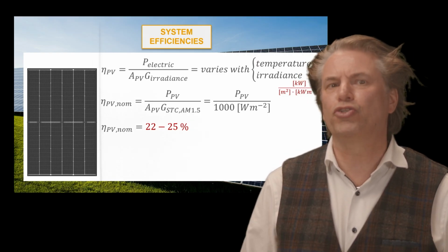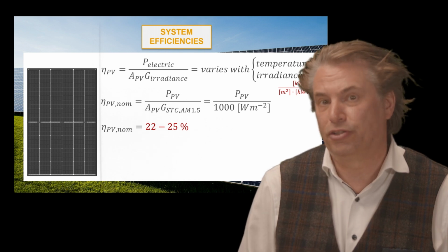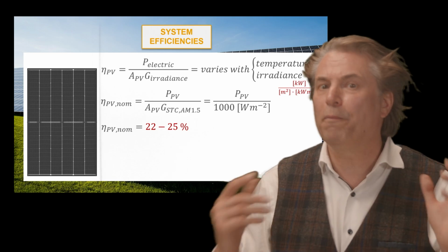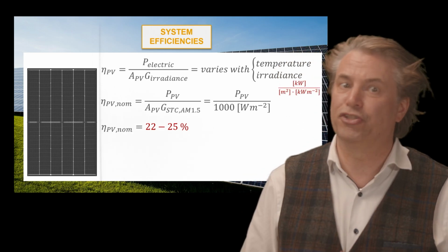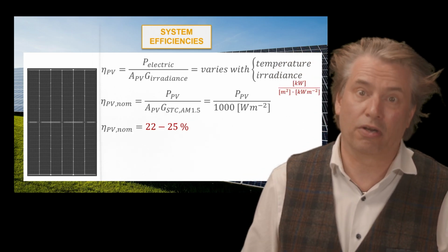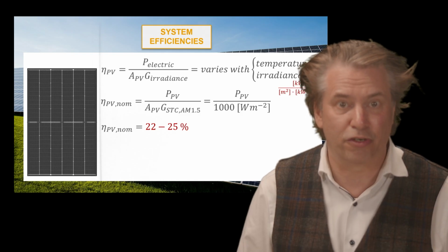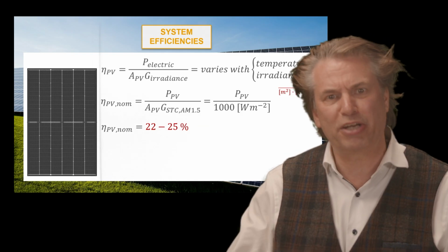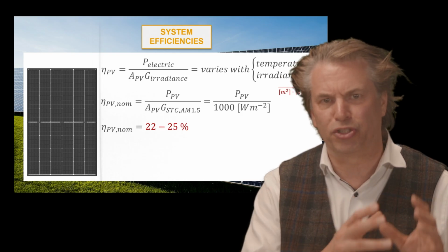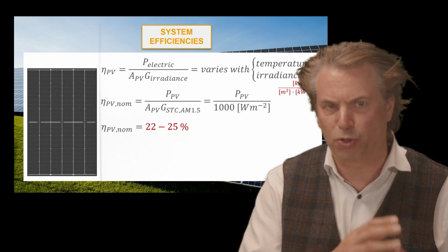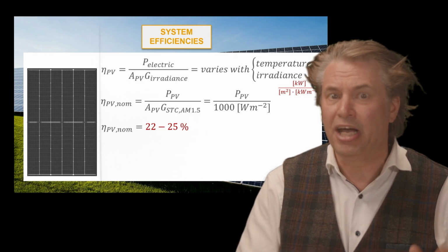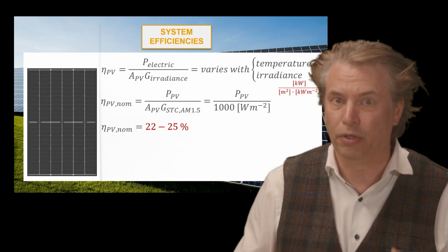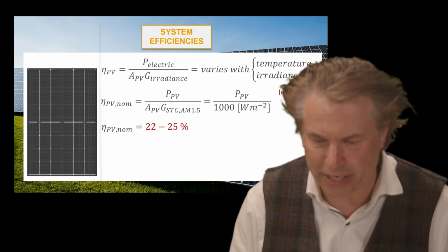The fundamental losses of PV modules are thermodynamic losses, optical losses like the reflection and the shading by contacts, electrical losses like the resistance and the recombination of the charge carriers, and the spectral mismatch of the semiconductor spectral response, resulting in thermalization of absorbed photons at high energy, and the inability of low energetic photons to be absorbed in the infrared.